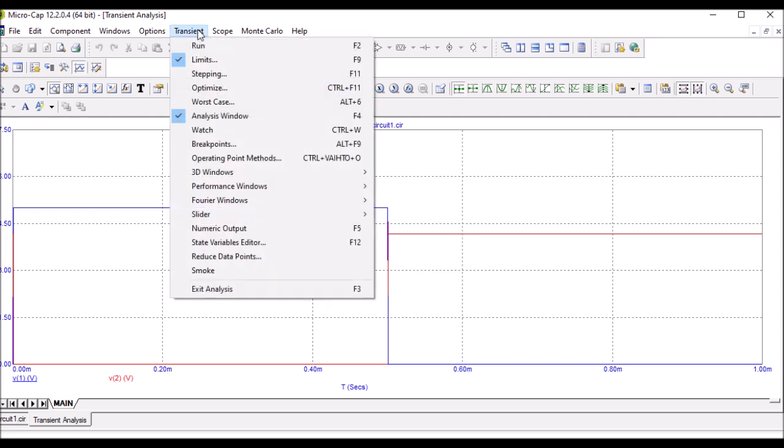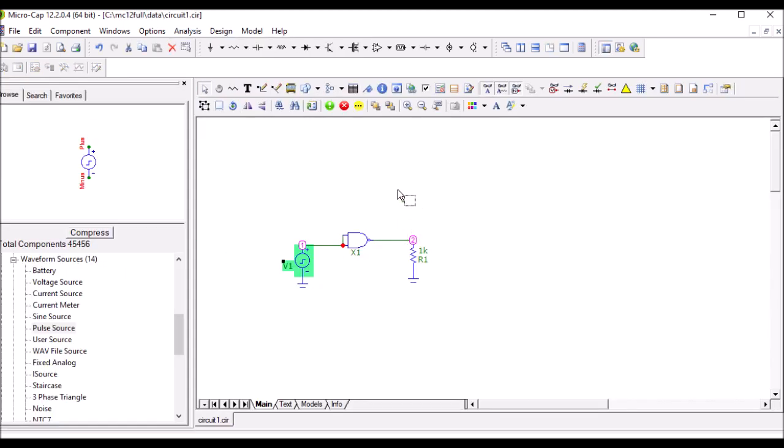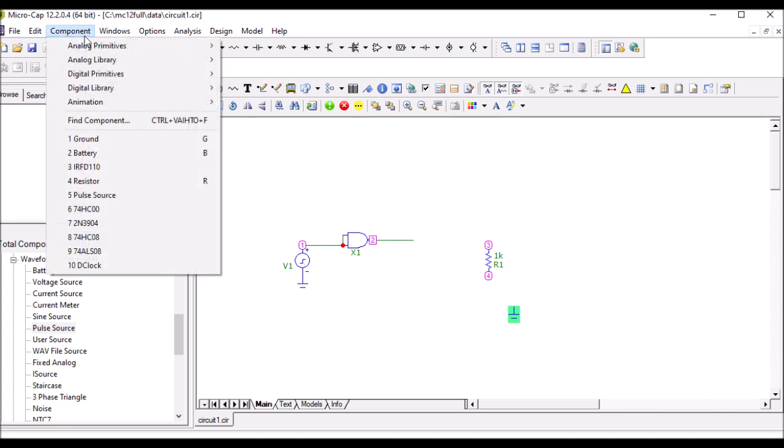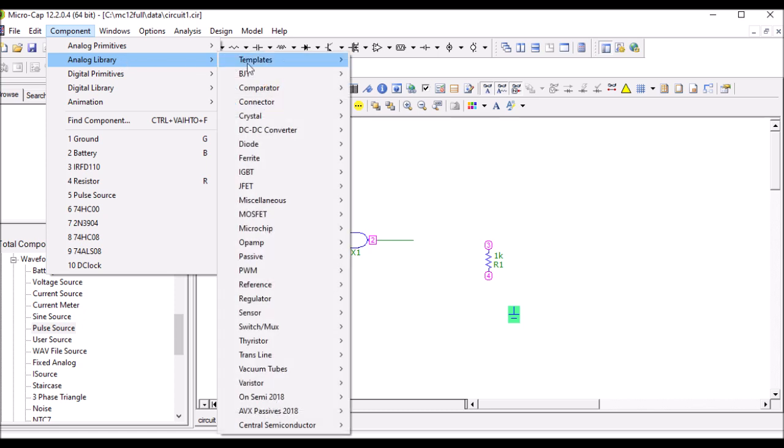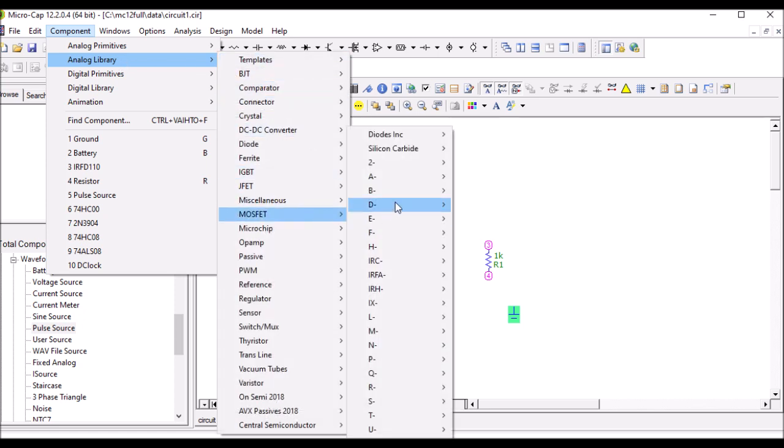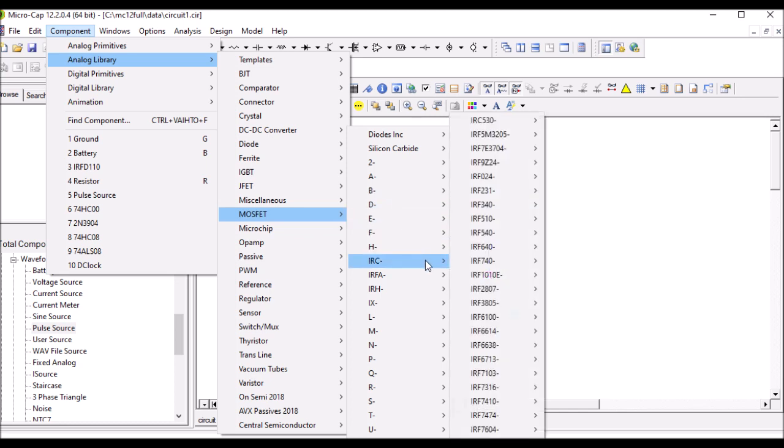Sometimes you need more if you want to control a 12-volt motor or 12-volt LED lamp or something like that. That can be organized, but you cannot drag more from a logic circuit because it's designed to handle voltages from 0 to 5. Instead, we will pick up a MOSFET as a switch,